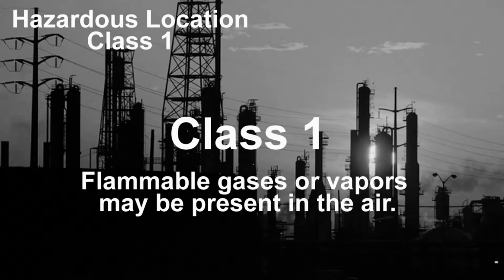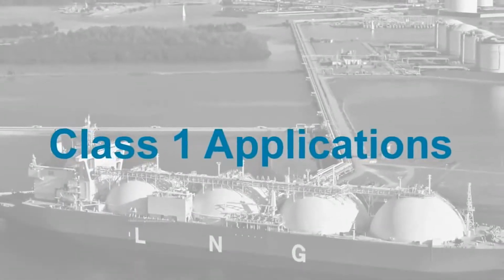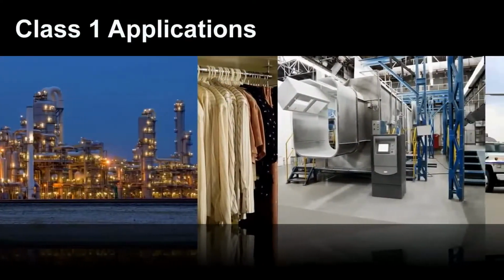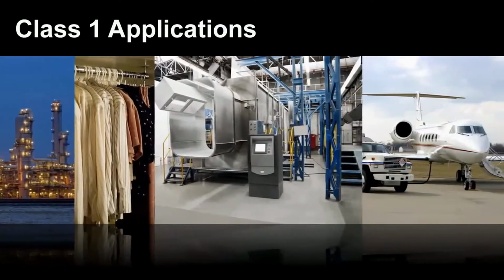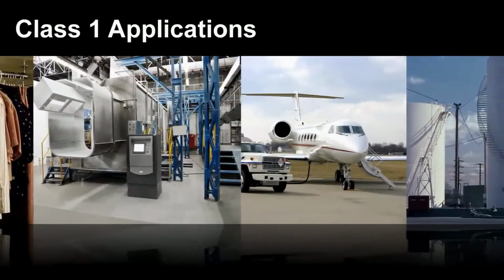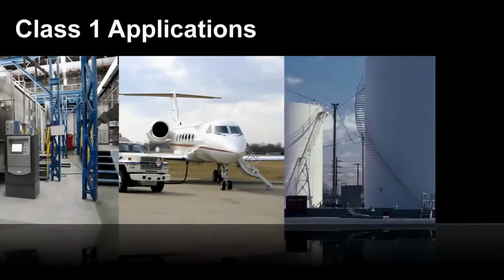So a Class 1 hazardous location is one in which flammable gases or vapors may be present in the air in sufficient quantities to be explosive or ignitable. Some typical Class 1 locations are petroleum refineries and gasoline storage and dispensing areas, dry cleaning plants, where vapors from cleaning fluids can be present, aircraft hangars, and utility gas plants and operations involving storage and handling of liquefied petroleum or natural gas.